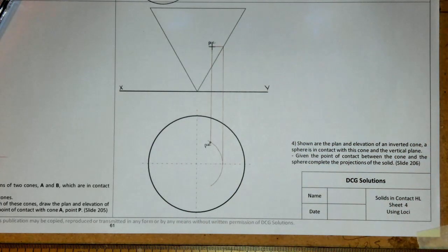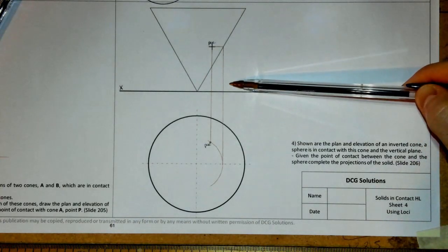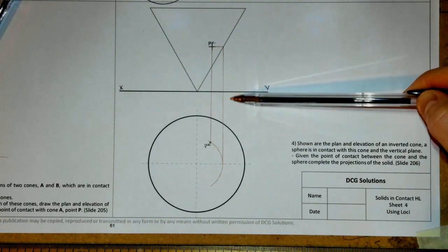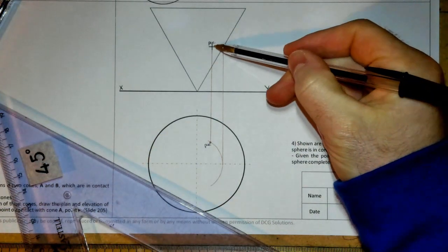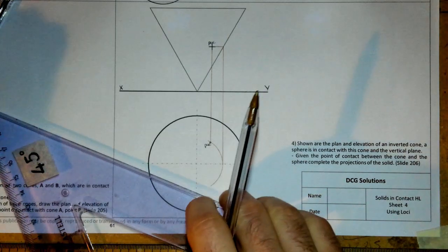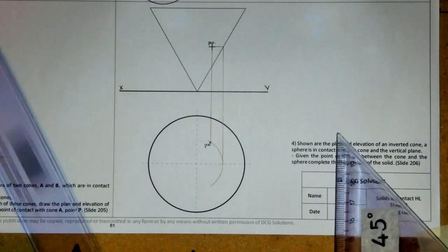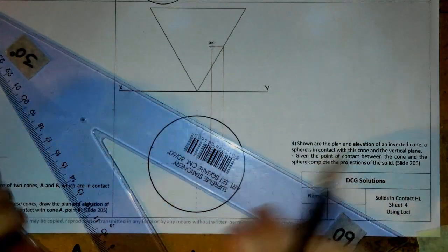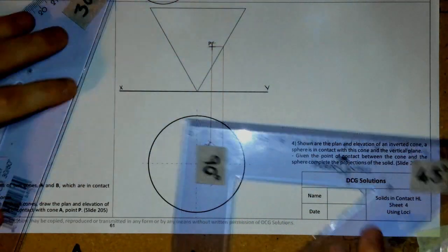This is similar enough to other questions we have done, like the very first question we did on this page, where we measured up from the XY line. Only this time we're probably going to be measuring down. So what we're going to use is the principle that when we have the point of contact, we've rotated around to our extreme generator, and anytime we get a ghost sphere, what we would usually do is go perpendicular to the point of contact when it's on the extreme generator.